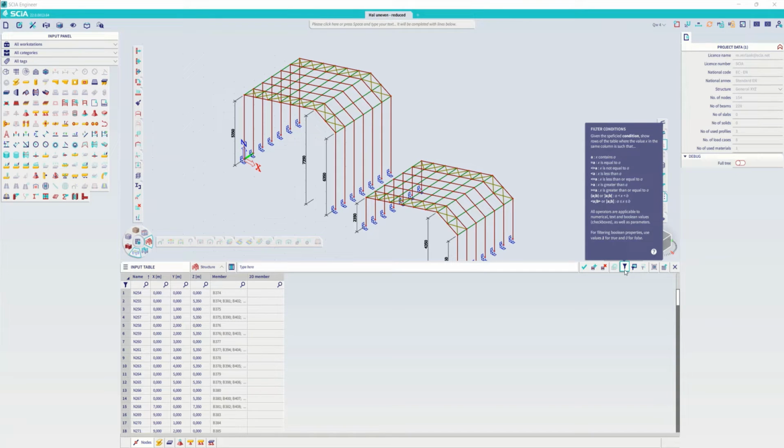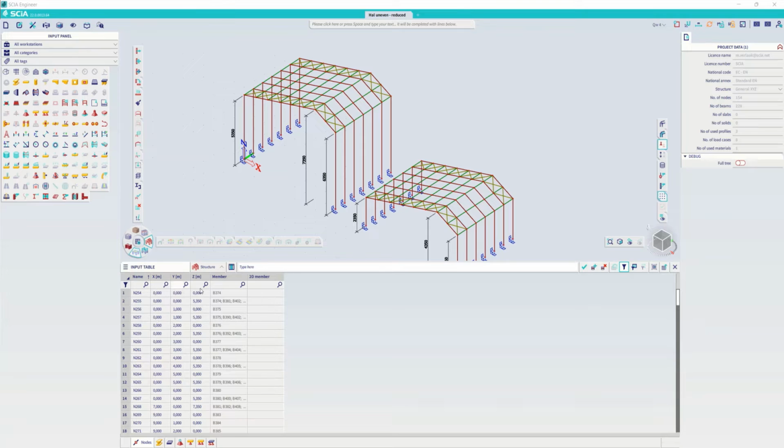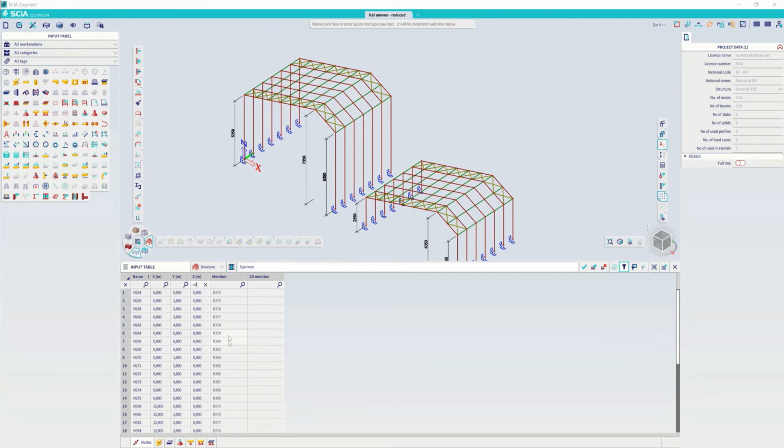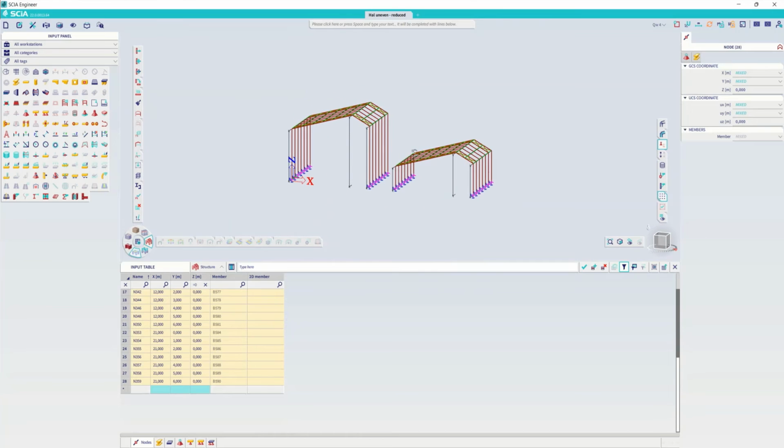So if you click on it, you can use the equal or lower than or higher than options and fill it in on top of each column to filter on certain cells. So for example, if I want to look for all nodes with a Z coordinate equal to 0, I can simply fill it in the search bar if the filter option is enabled, and I can find those elements, which makes it very easy to change some things in the properties panel again.